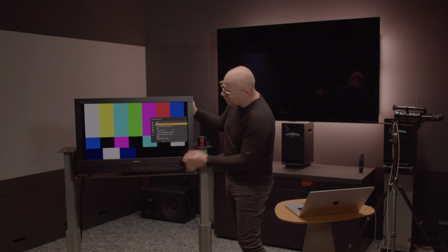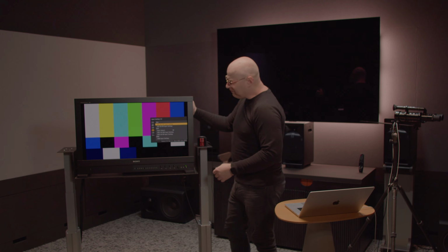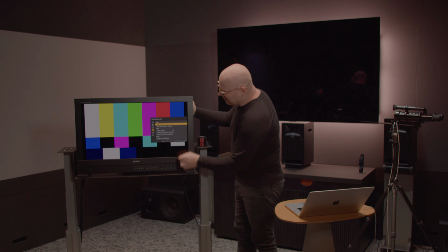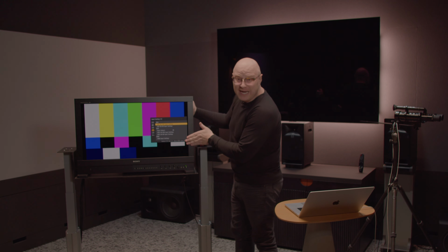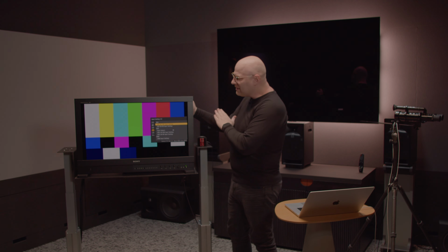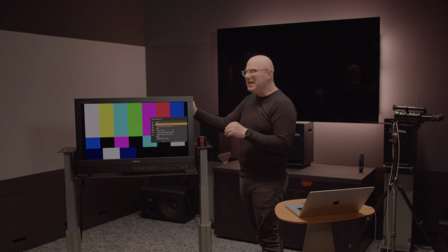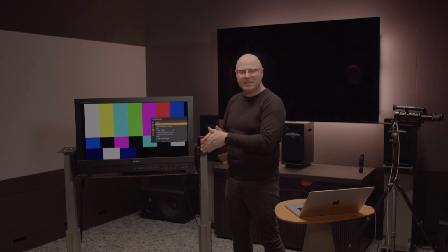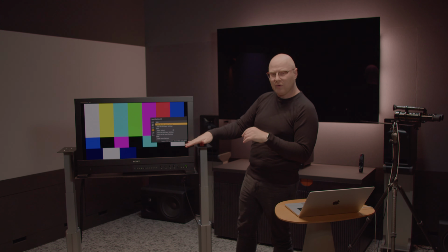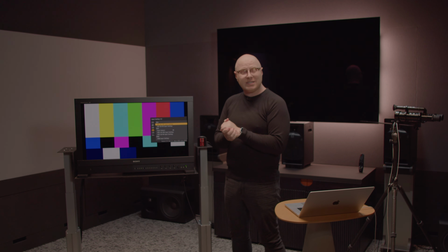So what we like to do when we calibrate these displays for customers, we meaning when I was a calibrator, but Portrait is we're teaching here, I like to set these up the same. Meaning whether you're on SDI1, SDI2, or HDMI, I like to set them up so all my input settings are the same. That way I can tell an operator, input setting 1, whether you're using SDI1, SDI2, or HDMI, is let's say BT709. If you're using input setting 3, whether you're using 1, 2, or HDMI, is going to be P3D65 HDR, let's say full range.